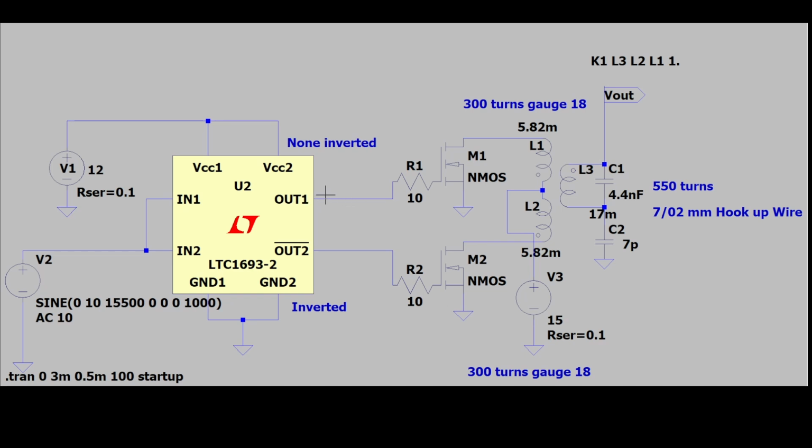Because you always have a voltage drop, and you have a time when the driver becomes active, which is 4.5 volt. That means if you go below 4.5 volt, it switches the MOSFET off, and if you get above 4.5 volt, it switches it on. So we technically have a window of 9 volt where the sine wave goes up and down, which means we have a time space in between, a delay in between, which allows for proper functionality without shorting the circuit.